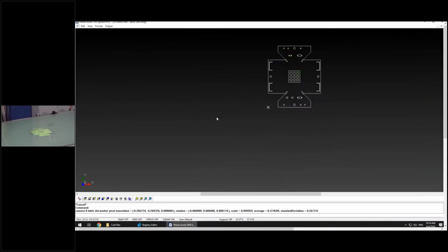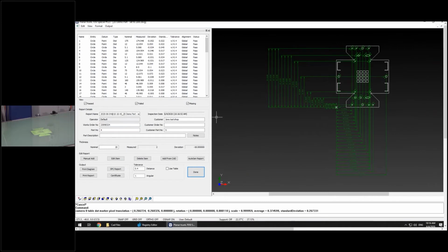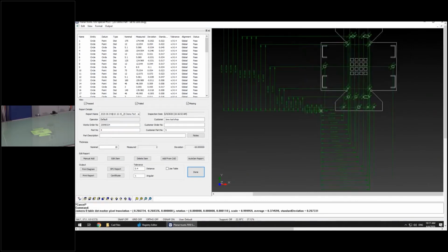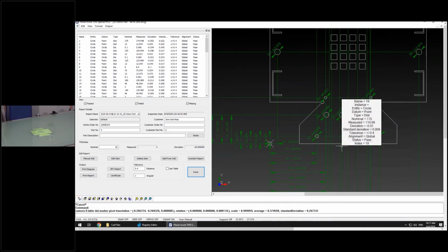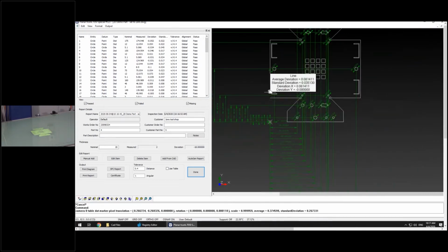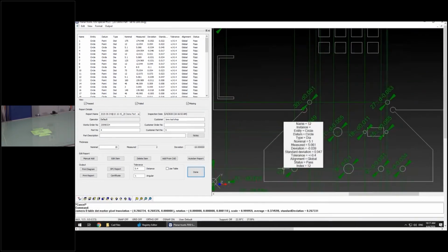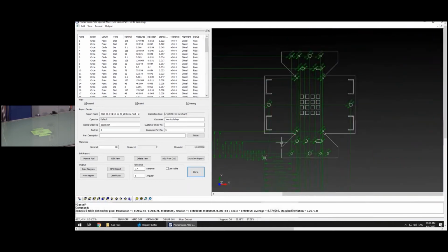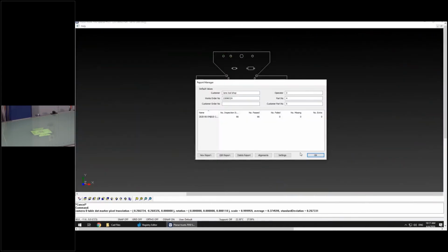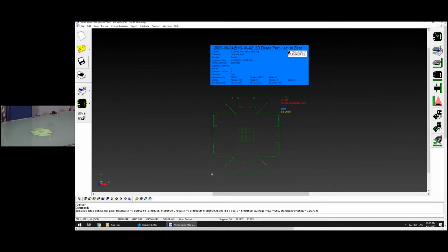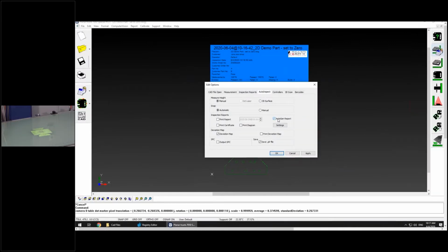And you see here, I now have 66 dimensions that are used from my nominal point. And my datum is going to be Y datum is here, X datum is there. And then it's able to calculate your diameters as well as XY locations of all those holes automatically. So I didn't have to program all that in there for me, those 66 steps. It just happened on its own. Again, kind of fun. That's only for if you're loading in drawing files, though, or DXF files.